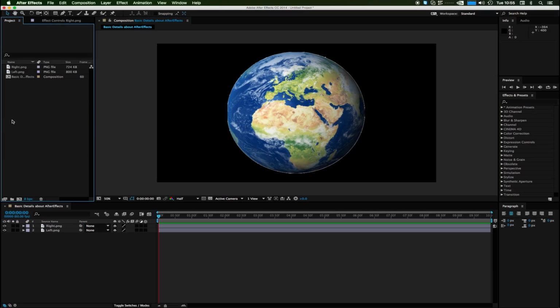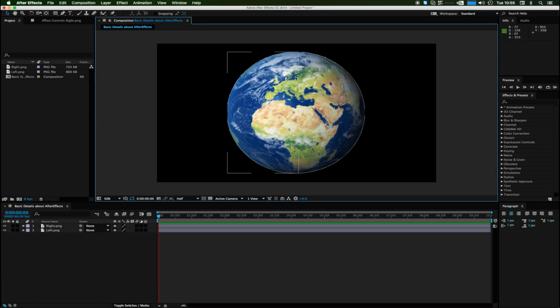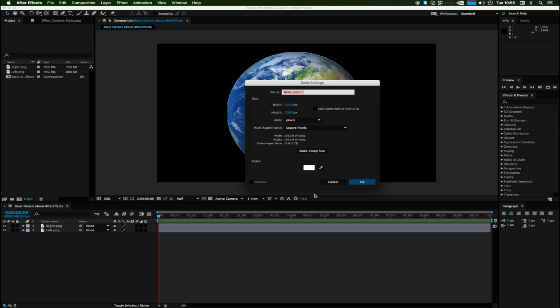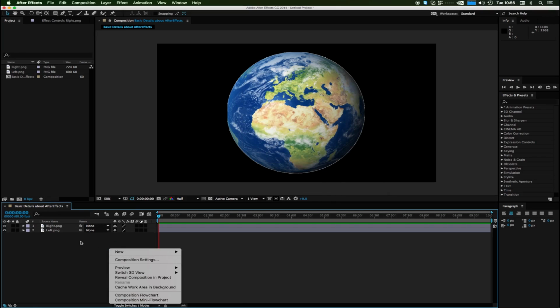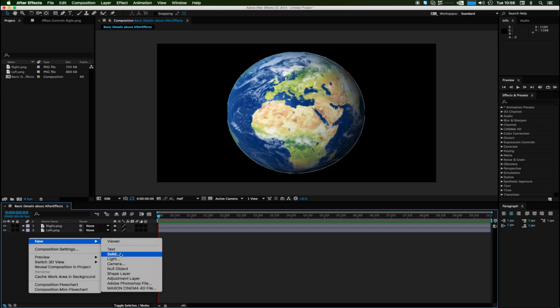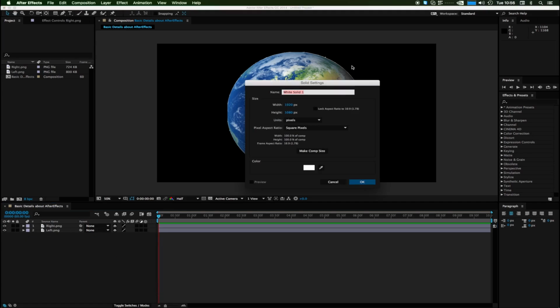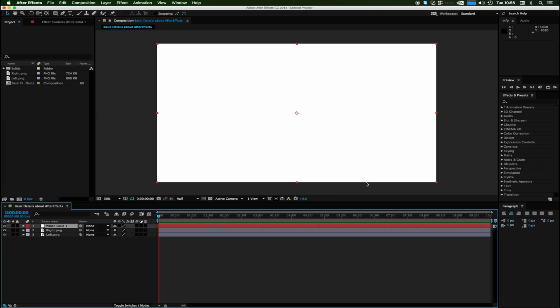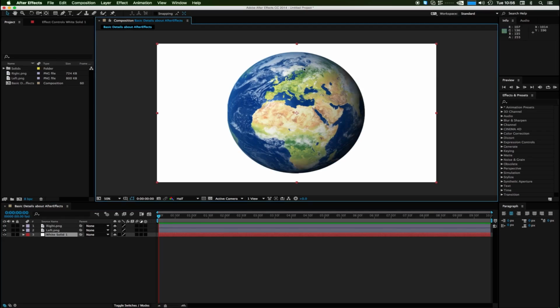Now the first thing you have to do is, if you want a background, you can have it, but I need a white one to make things go. We go to cancel, we go new, we click down here, right click, new, and we click solid. We go to color, we select white, and we press OK, and we press OK. Now this is the white color, and to make our globe visible, we have to grab it down to the bottom. Now you can see we got our globe in the center, which is in two parts, left and right.